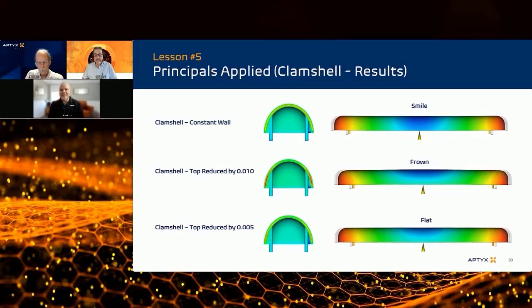Most of the time when I see correlation issues, it's operator error, meaning they didn't look at the material data, it wasn't complete enough to get accuracy, or the setup didn't mimic the actual process. That's the bulk of what I see. It's a very small percent, less than 5%, where it may be solver related. There are some tricky things where we might run into that, but predominantly we're pretty spot on.